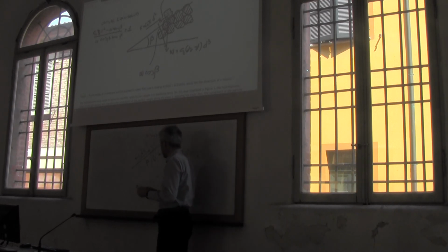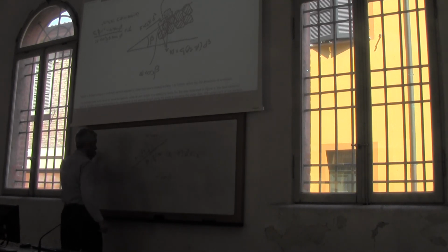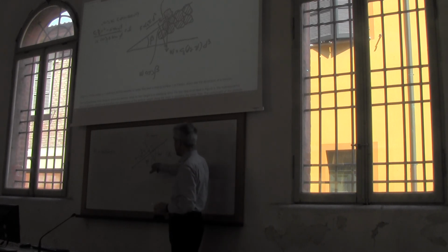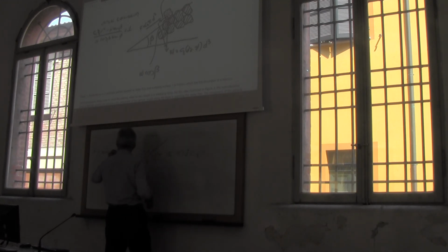So we are interested in the condition in which F is equivalent to W sin beta plus friction, and the friction is given by W cos beta, the component of the weight of the unit perpendicular to the side, times the friction factor, that is tan phi.